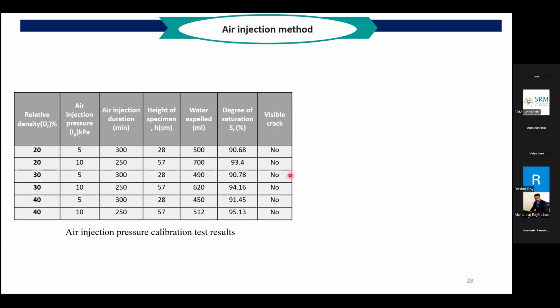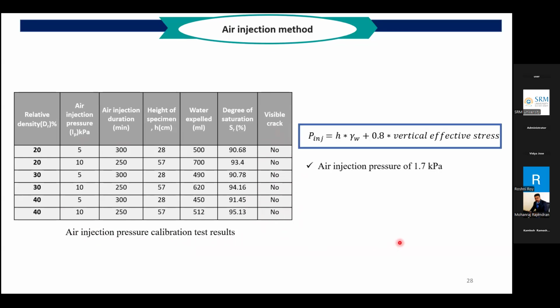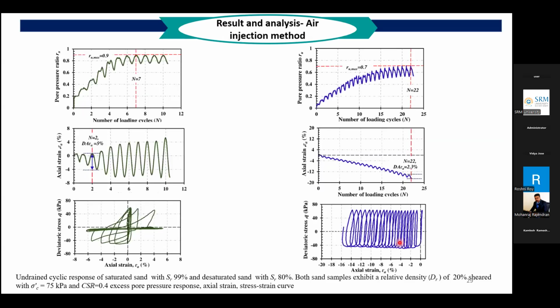Fortunately, no cracks were noticed for this particular condition. So this condition has been stabilized. We used a simple theoretical background to maintain the air injection pressure in such a way that the pressure is always less than the overburden pressure of the soil. That is how the condition is stabilized.